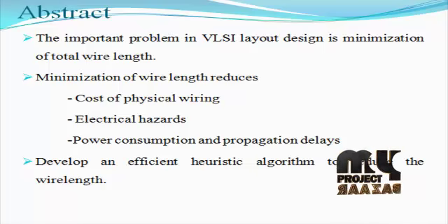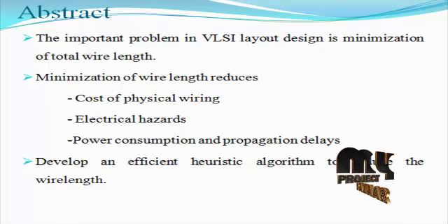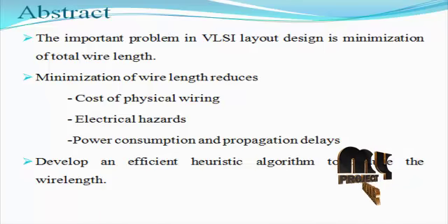Terminals assigned the same integer number are to be electrically connected and are called a net. A channel is usually specified by the netlist or channel specification. If a net contains only two terminals, it is called a two-terminal net. A net containing more than two terminals is called a multi-terminal net. The span between the leftmost and rightmost columns of the net is called the interval of the net.